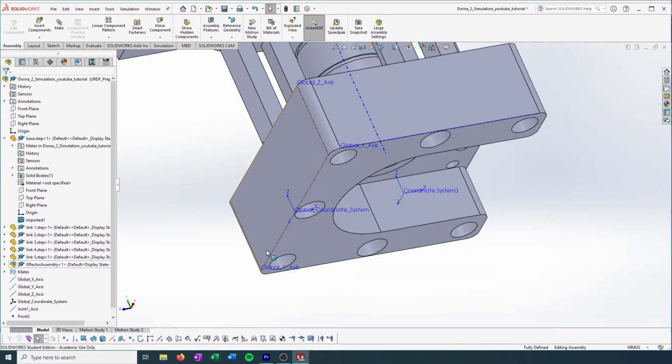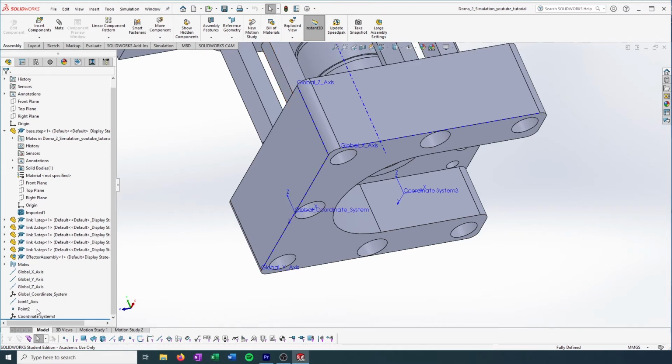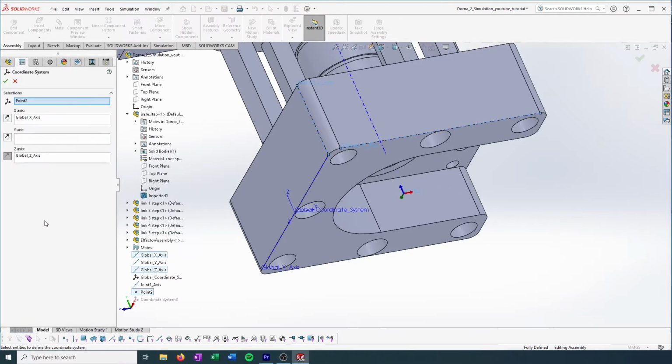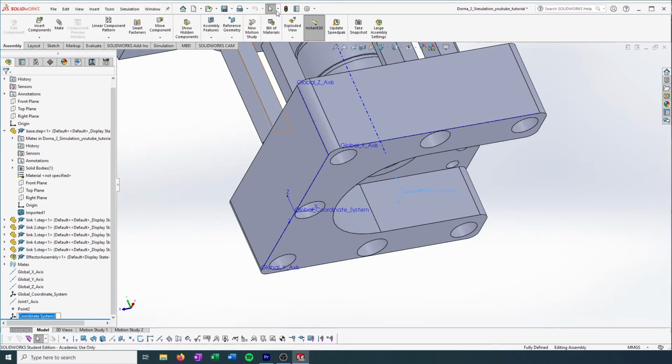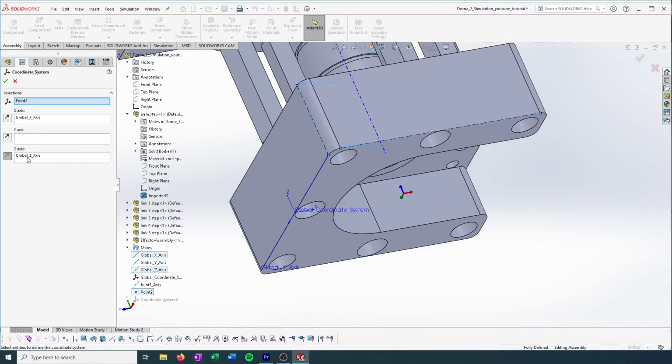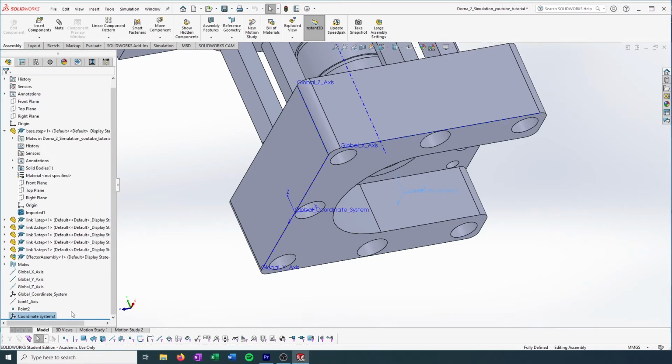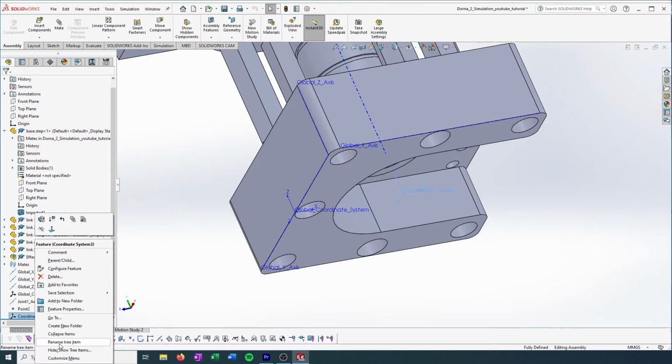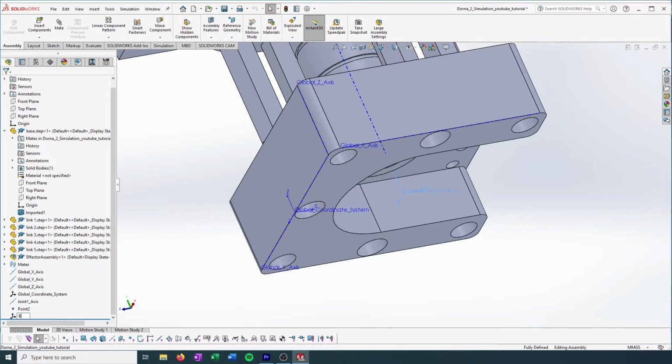So now let's check that, actually. So we got that. I'll save it. Let's update it. Now let's see if it's actually giving us any funny business here. Nope. Huh. Okay, so I guess when I'm recording, it doesn't do anything funny. Maybe it's because I'm actually updating it. I wonder if I didn't rebuild it, if it would. That's something I was doing differently just now. Maybe you have to rebuild it after putting this coordinate system down if you don't want your features to disappear. But again, that's weird because it's only the coordinate system that has that issue. So I guess that's just the general weirdness of SolidWorks sometimes. All right, so let's rename this. So this will be our base.